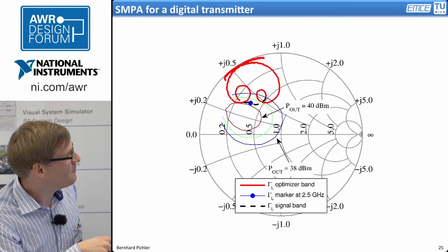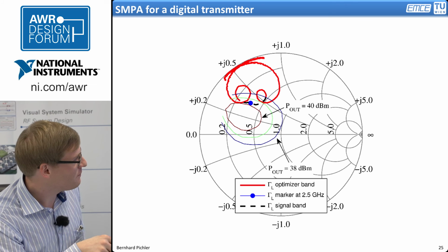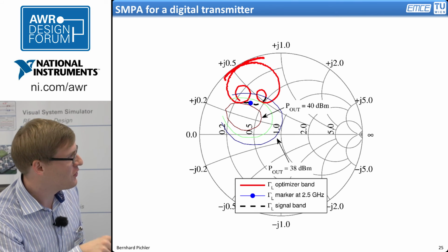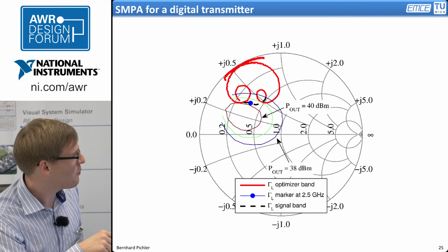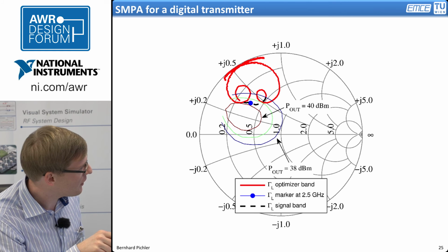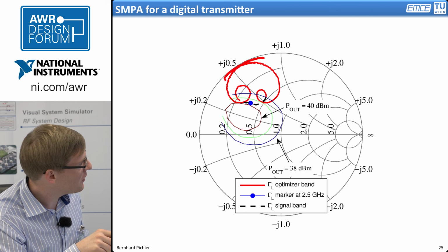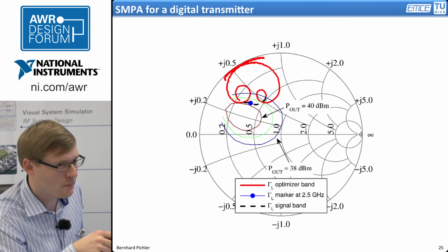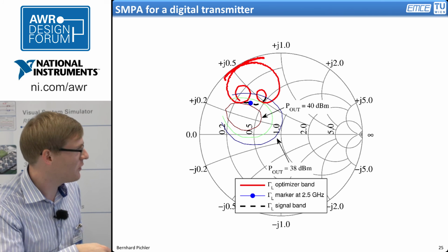Here you can see the matching network and the input reflection coefficient of the matching network and the filter combined. So you have a very good termination at the passband, which is here in the black curve. And outside the signal band, the terminations for higher frequency move up there, and for lower frequency again here. These are regions with very low power consumption for the transistor.